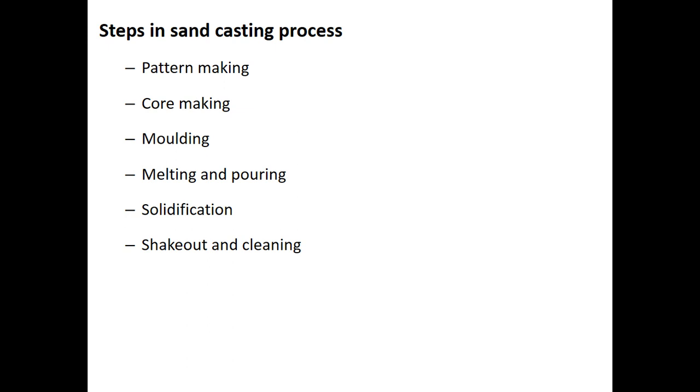And another one is the molding. It's a process of creating a cavity. In the sand casting technique, you create a void or cavity in a compacted sand mass with the help of a pattern.